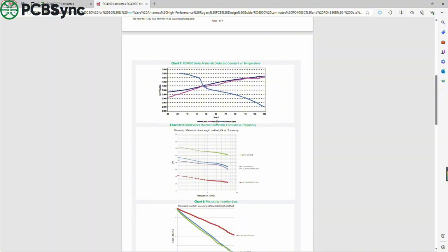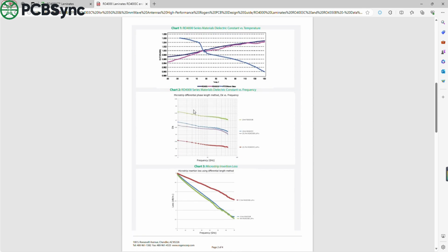DK stability is also very important, as it helps reduce resonance frequency and phase deviations between different batches of boards, but it alone can't guarantee the antenna's radiation pattern. The radiation pattern is also related to the ground plane, feed structure, installation environment, and array layout.